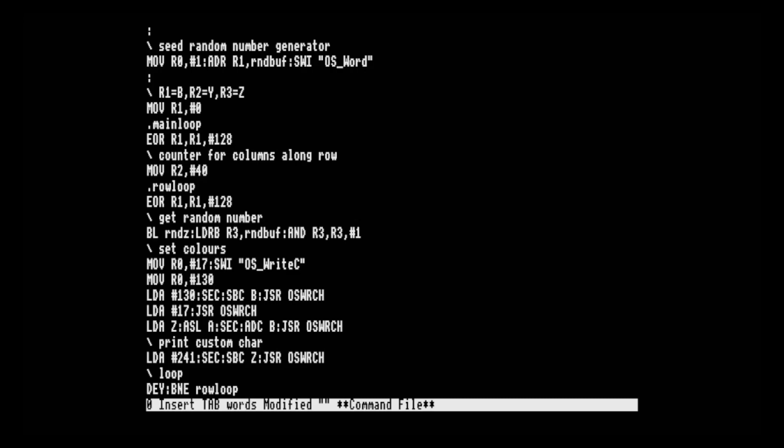Then we need to do this subtract of B, and before we had to explicitly set the carry flag because what we wanted to do is subtract B and nothing more, because if the carry flag is clear then B plus 1 gets subtracted. We just want to subtract B, but we can just do that with the sub instruction. Again, like the add one, there are two versions.